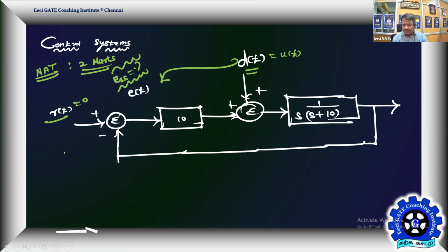There is one integrator. This is that integrator given. Your mind will say there is one integrator, step input, so error can be 0. But that's a concept only for the input command, not for the disturbance. You need to apply that caution because it's a numerical answer. You should not feed the answer as 0 by mistake. It may be 0 here also, but I'm not sure. We'll find out that answer, and see first how to play for this problem at time t equal to infinity.